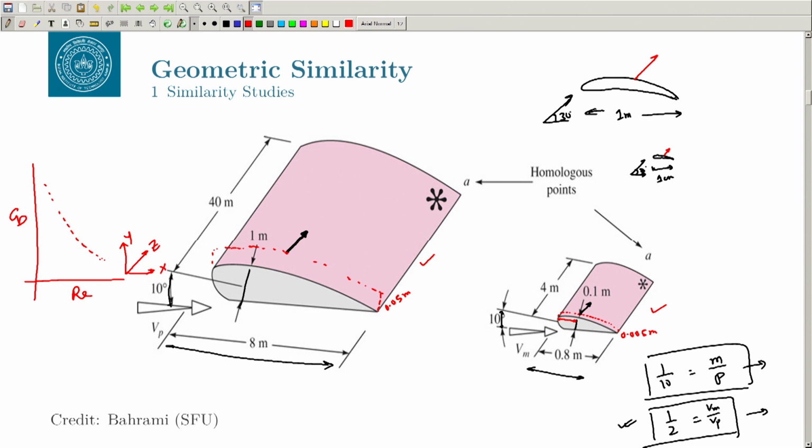Now, you might ask the question that the Reynolds number is a function of many different parameters, rho u L by mu, as you must have read in your fluid dynamics course: density, velocity, length scale and the viscosity. And here CD is basically D by half rho u square, and maybe the L square also if you divide by area, or some area.